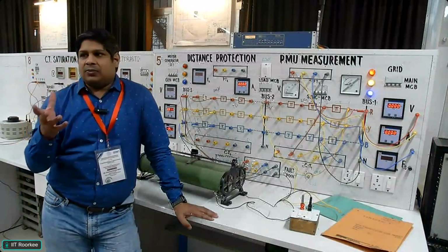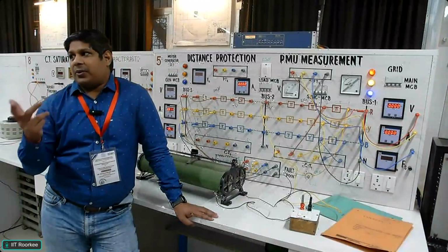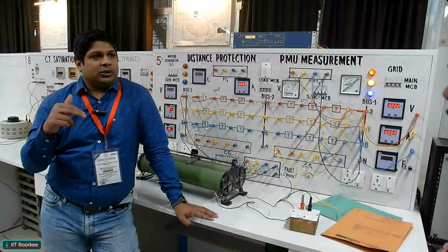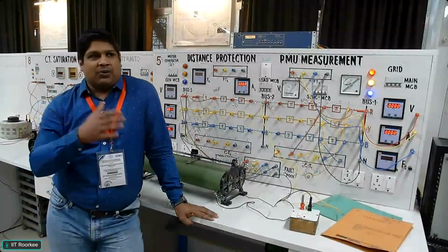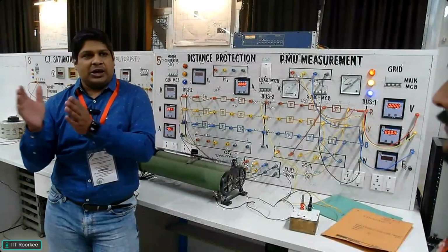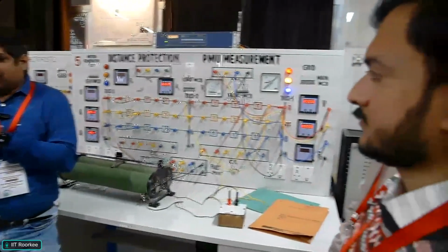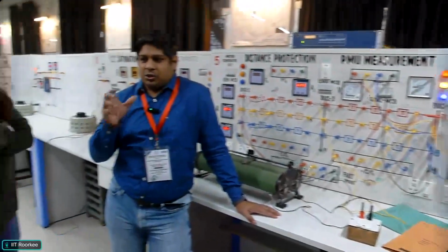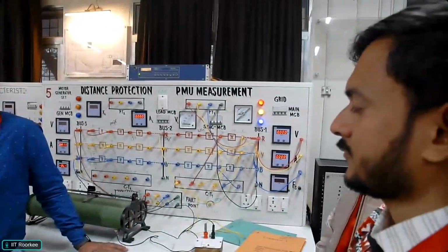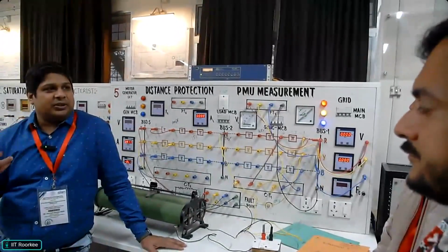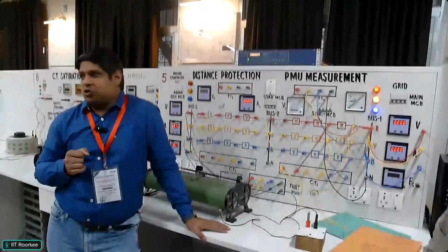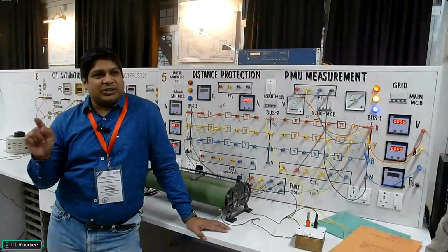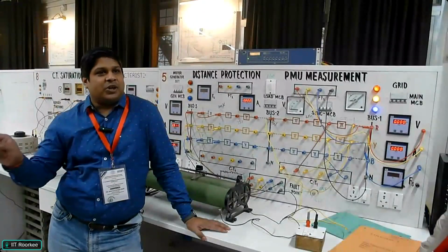So basically, why are we making this 3-zone protection? To give backup. Let's say we have R1, which is protecting the first line, and R2 is protecting the second line. And in the second line, at 40%, a fault has happened. In the normal case, R2 should detect it because it is falling under its first zone, so R2 should trip instantaneously. But if due to some mal-operation or misoperation, R2 fails to operate, then that 40% fault, from R1, is 140%.